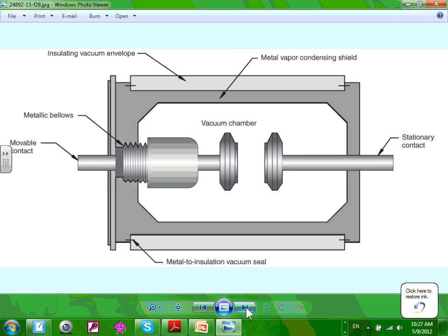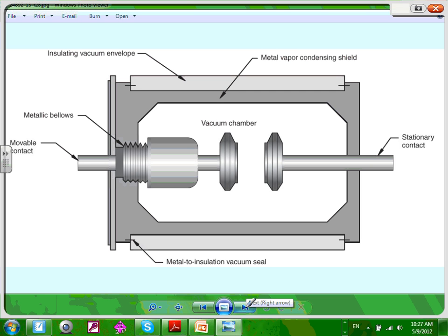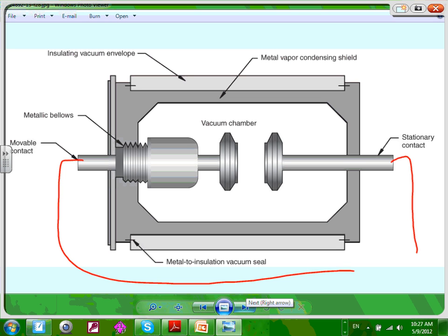Now the best technology obviously is the vacuum. The vacuum is really easy. You get rid of every type of gas, and you bring your 13.8K 1000 amp right in here, movable contacts, stationary contacts. And where do you do the interruption? Right here's your contacts. Now, very, very minimum amount of arc. Who cares? You don't have to go change the contacts every time you have a short circuit or an overload condition. Cool. And you have to seal that chamber. This is a cylinder, vacuum insulated cylinder. So you have to seal it and do all the sealing for the vacuum and so forth.